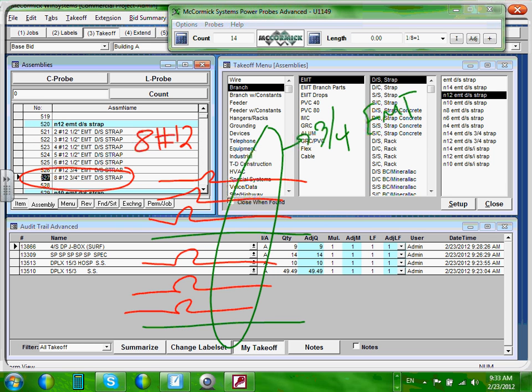That's the assumption. All these you can see are 20 amp circuits, right? These are 20 amp, 20 amp. And everything here is feeding receptacles. So 8 conductors, that's what you're doing. You're grabbing 8 conductors coming from 6 circuits, 20 amp, to go feed multiple receptacles or lights or anything.